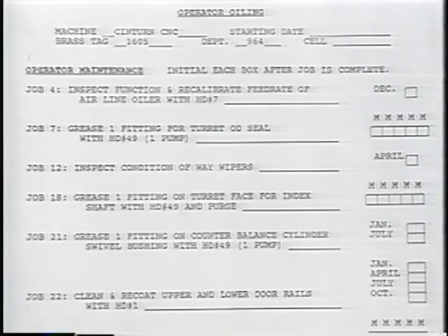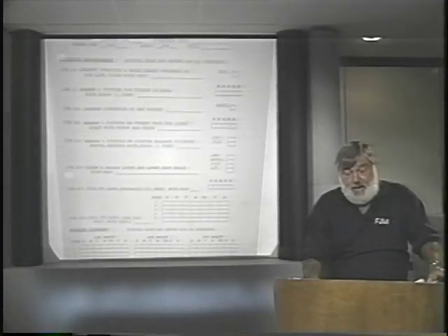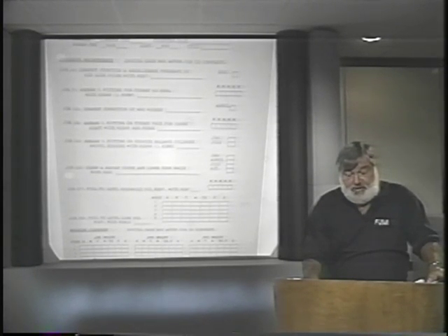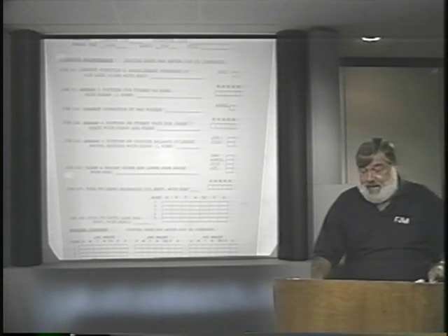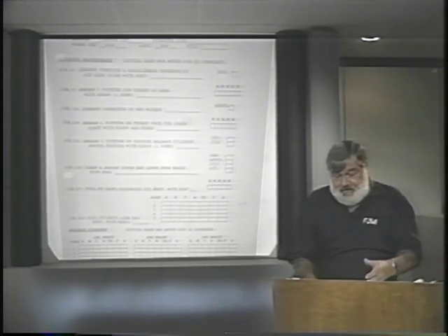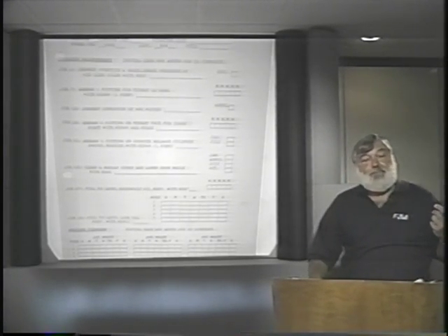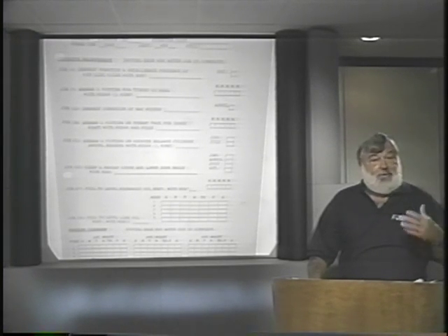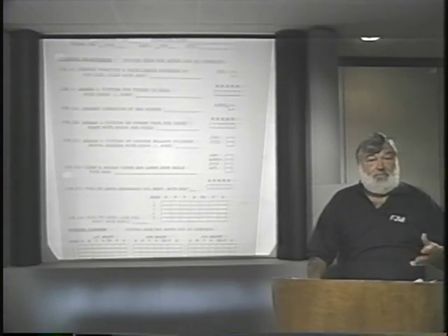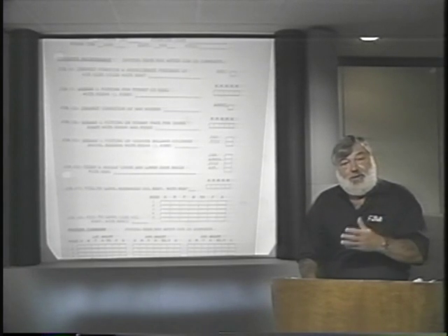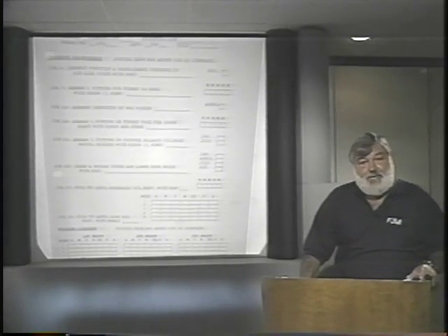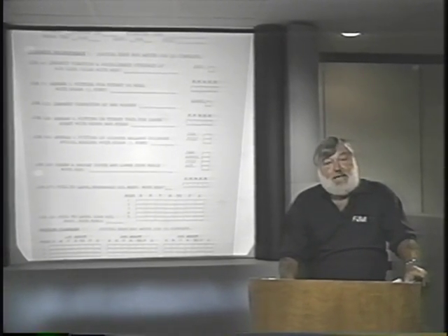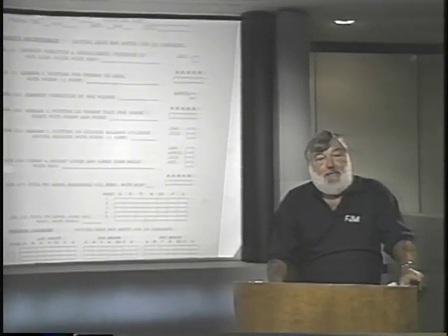The operator has to literally check off based upon the frequency relative to those particular lubrication instructions, and on a weekly basis this document is picked up and reviewed by not only the supervisor of that department, but it is then forwarded to the maintenance department for review, subsequent recording into the PM program, and then filed.